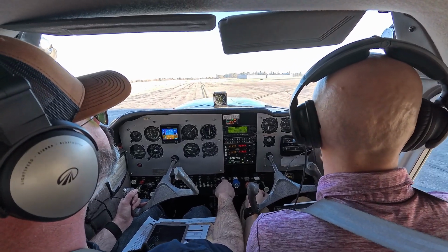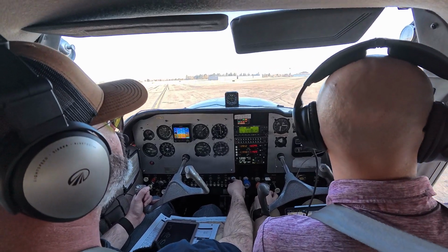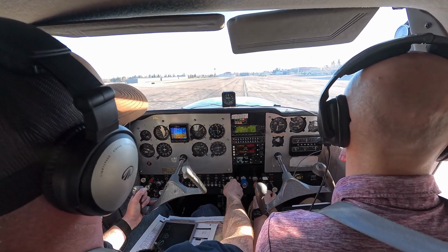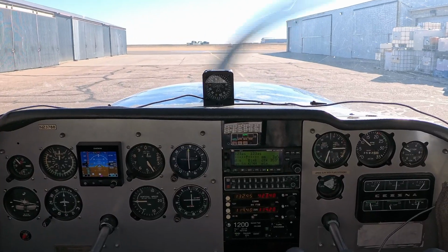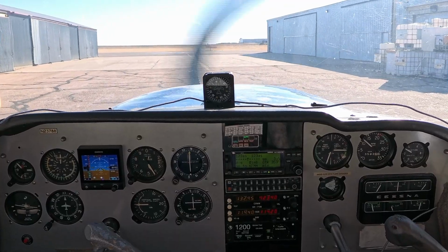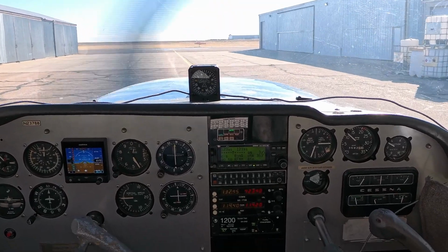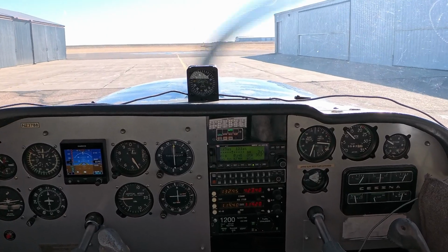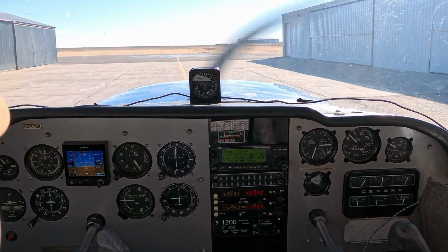Normal ground operations usually don't have high engine power, which means we're not putting enough power to the airplane to supply the maximum RPM which we have selected with our high RPM setting with the blue knob. So, taxiing around should be relatively easy. Should be relatively straightforward to what you're used to with a fixed pitch propellered airplane.